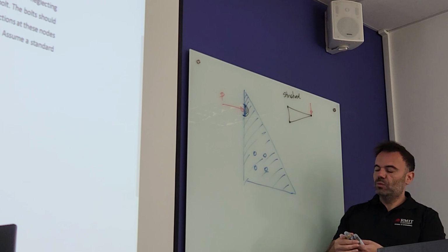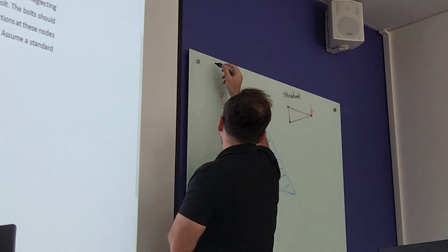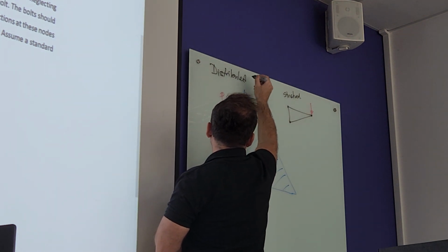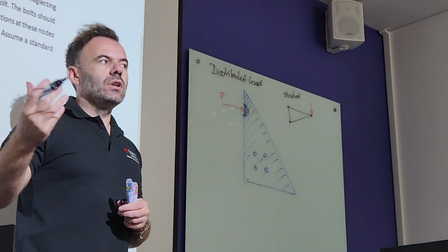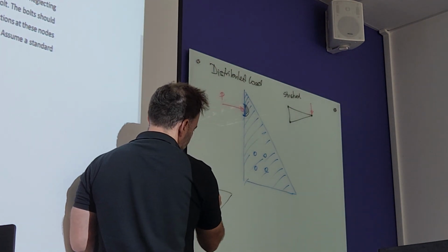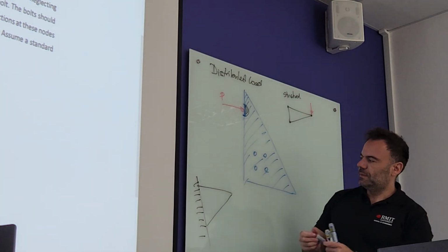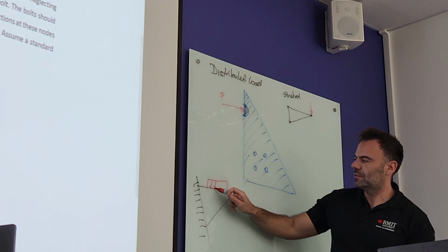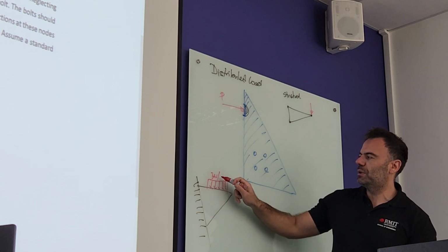An alternative to that would be to apply something called distributed load. I think you faced this in Solids 3 when you had a structure that looks maybe like that. Sorry, probably the guys online can't see it. It gets represented like this, and it tells you 3 newtons per millimeter.